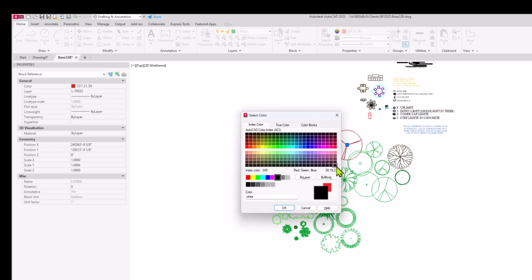Once we get into making our drawings more hand-drawn, we can do that through the plotter interface by assigning some of these colors different line weights. So we can actually gray out lines in the plot settings when we move forward into finishing our drawings. So I'm going to say OK for now.